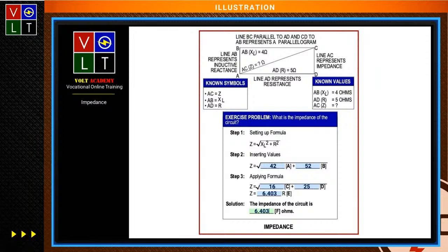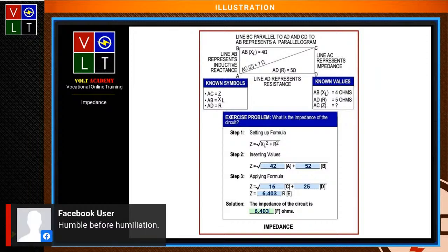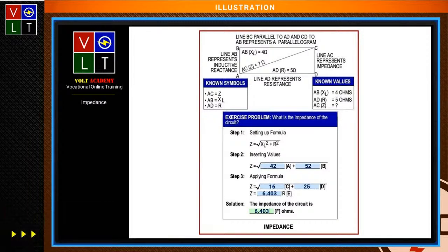When you look at this, just tying this together, you take the resistance, capacitive reactance, and inductive reactance, and when you add those together, what is that called? The impedance. Okay, so the way I like to look at this when I'm explaining it: in determining the capacitive reactance, inductive reactance, and resistance, you cannot just take those values and add them together. The main reason behind this is because capacitive reactance and inductive reactance in alternating current circuits have an opposite effect.